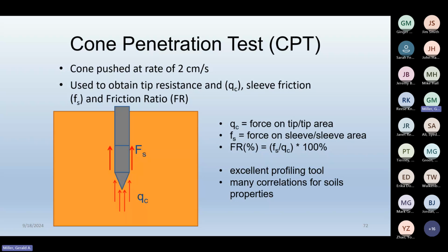Because what happens in an unsaturated soil, when you start pushing that cone into the ground, first of all, you tend to get significant dilation, which is a tendency for volume expansion right around the position of that porous element. That tends to create a negative pressure of suction, which actually pulls the pore fluid out of your sensor.